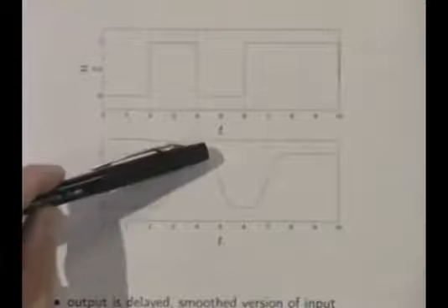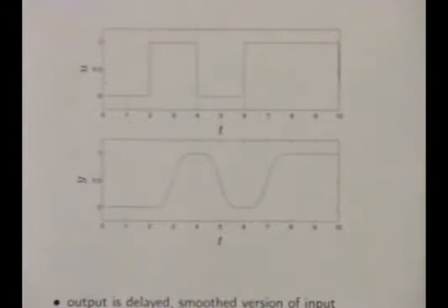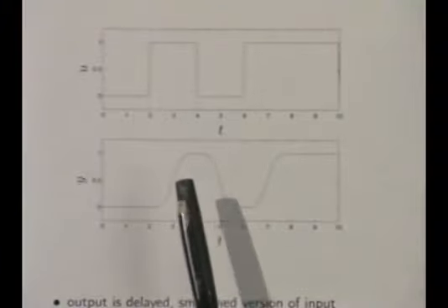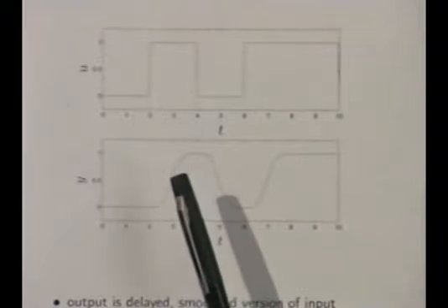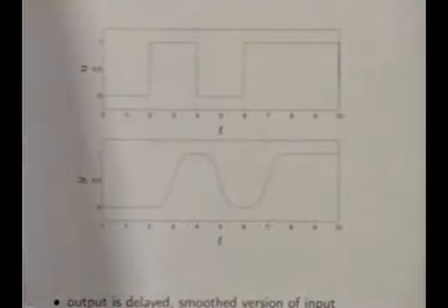I mean, it would if you had a 2-foot wire and the time scale was slow enough. So when you hook up something to an oscilloscope, your assumption there is it's perfect. But when it's 2 miles of wire, this is not the case. Okay? So then someone says, okay, what has happened to the signal? And you look at it and you say, it's been smoothed. But that's obvious, right? But the other thing you see here is it's been delayed about 1 second. So this should fit intuitively very well with you as the convolution of this and the impulse response, which is here.